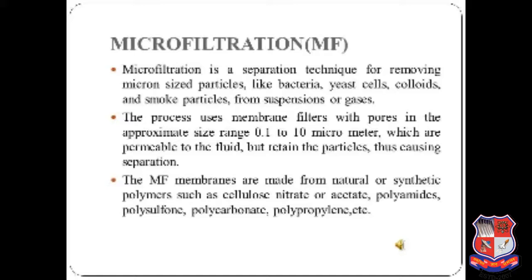Microfiltration is the process of filtration with a micrometer size filter. The filter can be in a submerged configuration or a pressure vessel configuration. They can be hollow fiber, sheet, tubular, spiral wound, hollow fine fiber or track-etched, etc. These filters are porous and allow water, monovalent species like Na plus and Cl minus, dissolved organic matter, small colloids and viruses through, but do not allow particles, sediment, algae or large bacteria through.